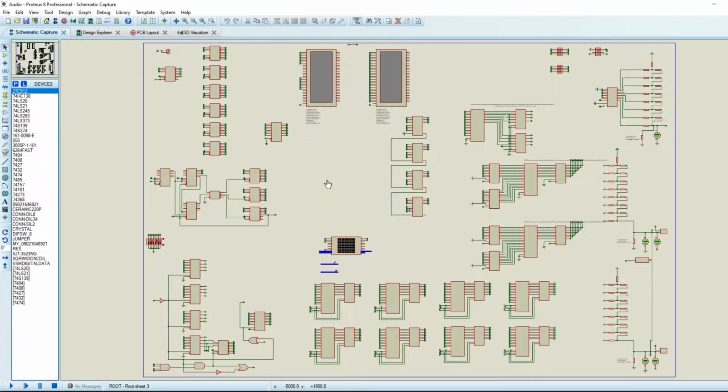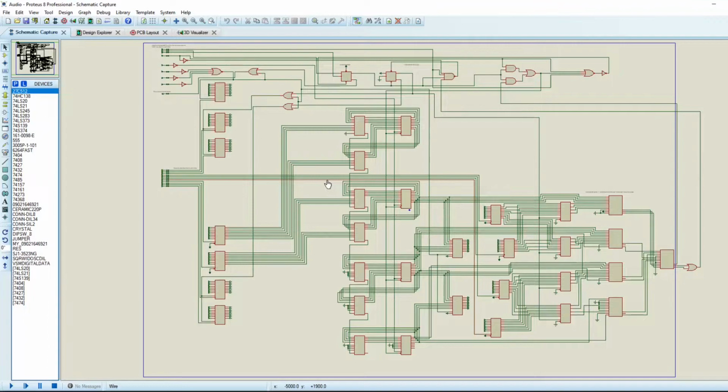Now, with this PCB design tool, I can take one schematic and duplicate it X number of times. It's using a sub-circuit mode, where I can duplicate this schematic quite easily without needing to rename all of these input sources and everything. Basically, this is the schematic which handles the state and common read address calculation and all of the voice looping logic for one voice.